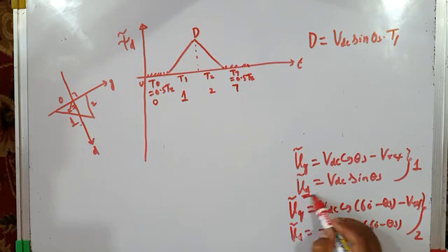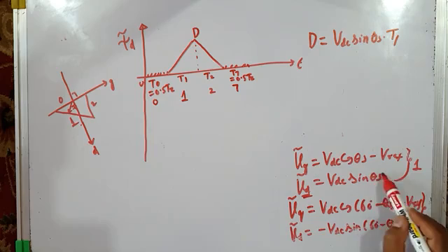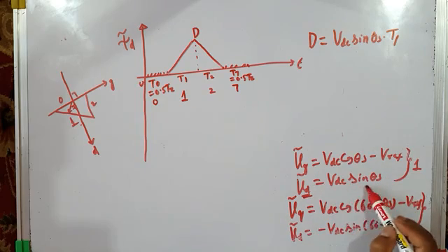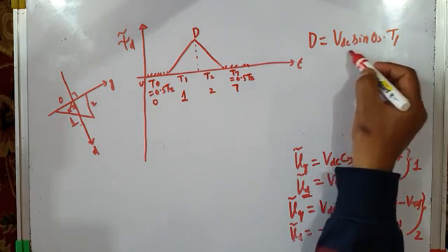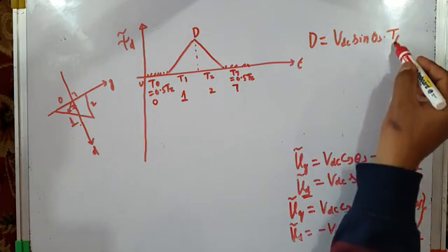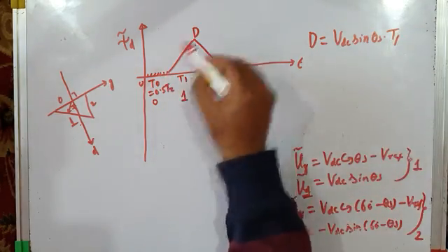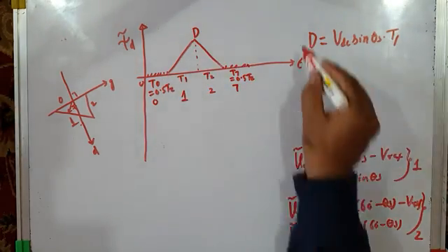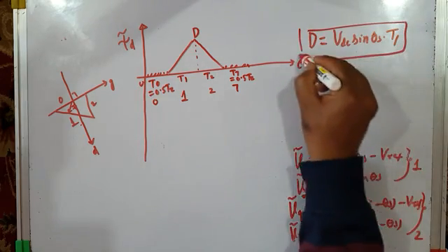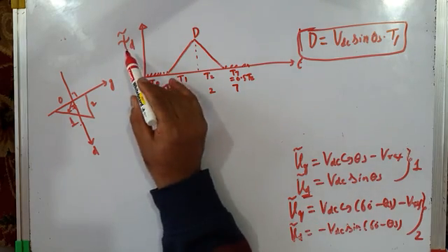We have just found that when active vector 1 is applied, the d-axis component of the error voltage vector is VDC sine theta s, and this vector is there for time interval t1. So if I multiply VDC sine theta s by t1, that will give me d. Keep it preserved for the time being because I require it later on. So this is about psi d tilde.